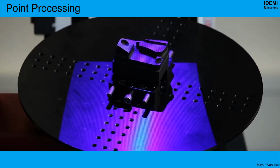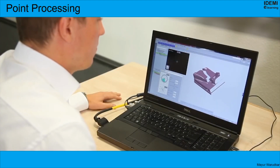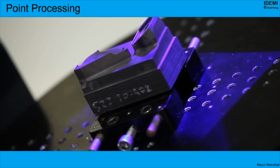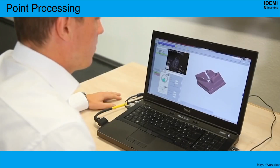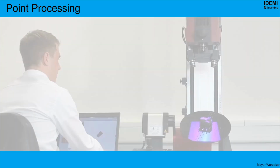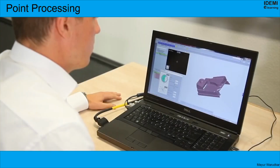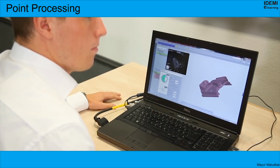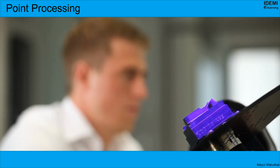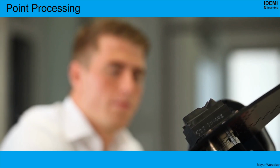This phase also allows us to merge multiple scan data sets. Sometimes, it is necessary to take multiple scans of the part to ensure that all required features have been scanned. This involves rotating the part, hence each scan datum becomes very crucial. Multiple scan planning has a direct impact on the point processing phase. Good datum planning for multiple scanning will reduce the effort required in the point processing phase and also avoid introduction of errors from merging multiple scan data.